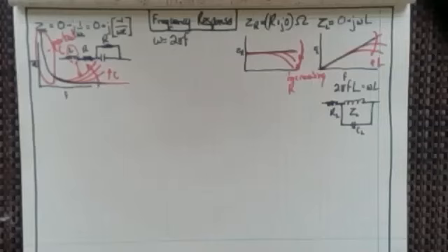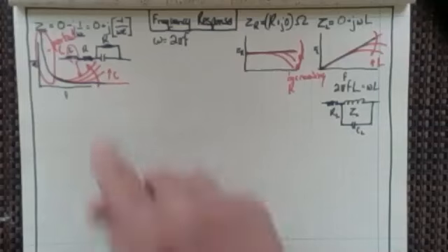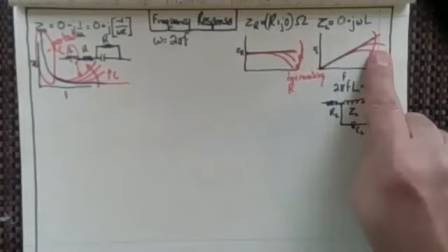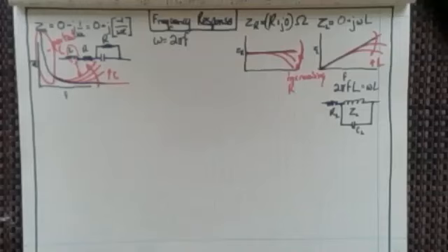So what I want to get into now isn't the frequency response of the individual components and how those deviate from theory into reality, like I've shown you here with how these really work at extremely high frequencies. And what I mean by that is 10 megahertz and above. You don't really see a lot of change unless it's a very, very large resistor. You're not going to see a lot of change up until about the 5 to 10 megahertz range. So most of the things that we're doing are much lower than those frequencies, so we don't have to worry about designing for high frequency.